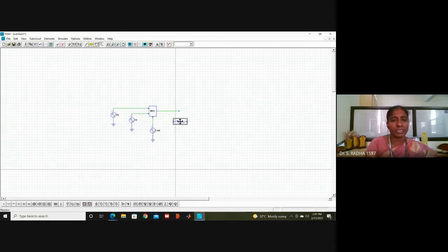So I will put a resistor, select that and click on this rotation. The resistor will come vertical. Take a ground and connect to the ground bottom side of the resistor. Okay, and take the wire, connect this resistor to the output. This is additional, I am simply doing it. It will not have any effect on the circuit. Just to avoid the hanging of the output voltage. Okay, this is my circuit.